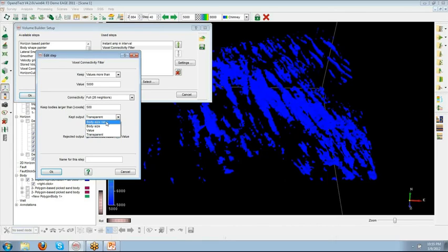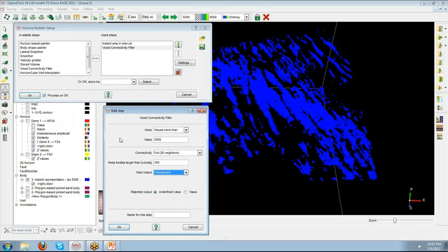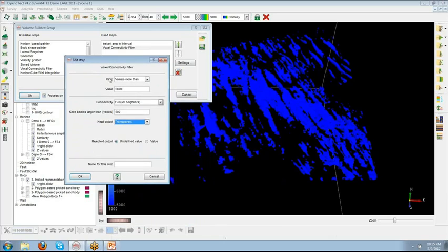Or we can decide to output other features that are not available with the standard implicit representation, and these are namely the body size rank, which will be from 0 to as much bodies as we have, with 0 being the largest volume, 1 being the second largest, and so forth, so by decreasing size. And we can also output the body size itself in number of voxels.